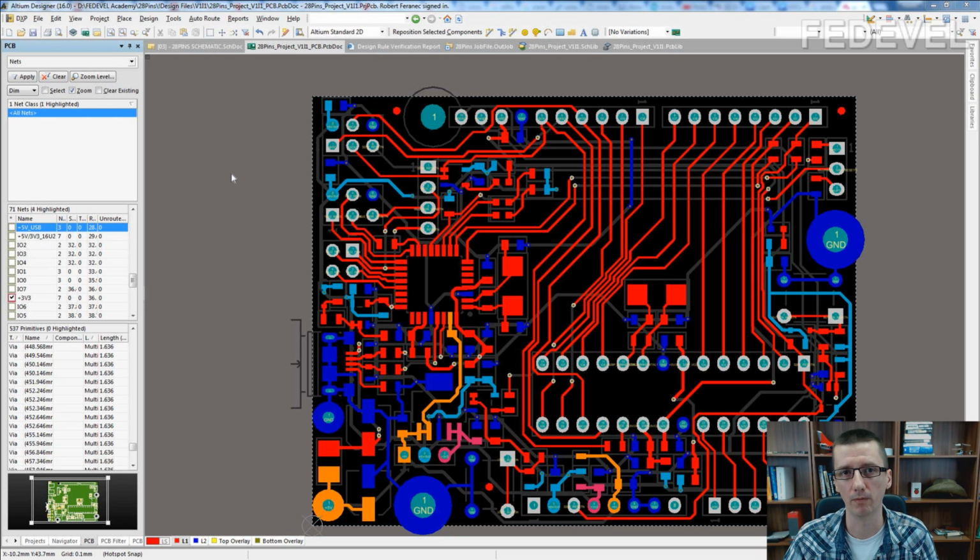And for example, one of the biggest differences is that in a complicated PCB, you really would like to place all the vias before you do the layout, before you draw the tracks. So for example, the ground vias, the power vias, you need to place them there. What do you think? Why? Because if you don't have space, you really don't want to keep rerouting the layout.